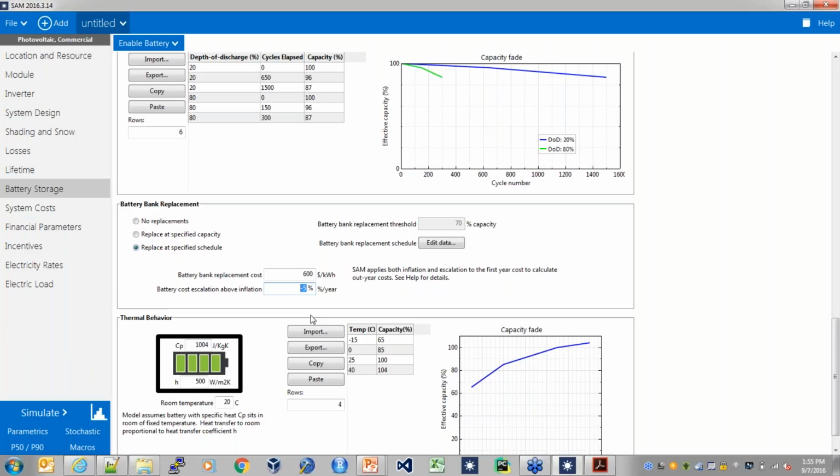It is lost through the power converters, and then there is also the concept of round-trip efficiency. So as the battery charges and discharges at different voltages, you might discharge a slightly lower power than you charged. However, we don't over time degrade the amount of capacity in the battery.